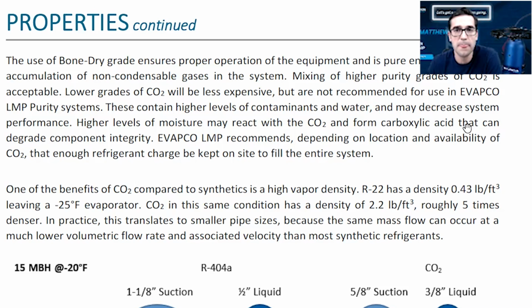What's the purity level? And I really believe you should be doing those maintenance processes, like changing the liquid line filter dryers anytime you open up the system. When you're doing an oil change, you should be changing everything: the oil filters, the oil separators. You should be cleaning all the screens. Don't be just doing one thing. When you're doing that job, do the whole maintenance, so you don't have to go back and worry about it later.